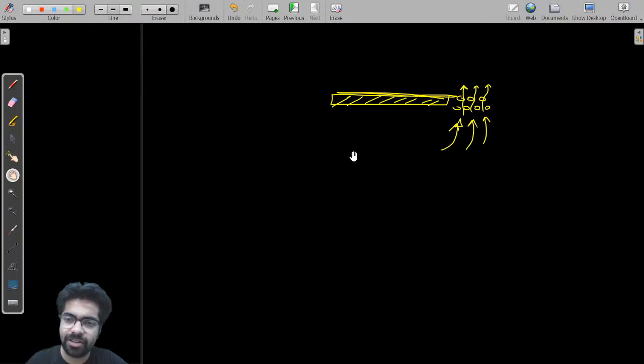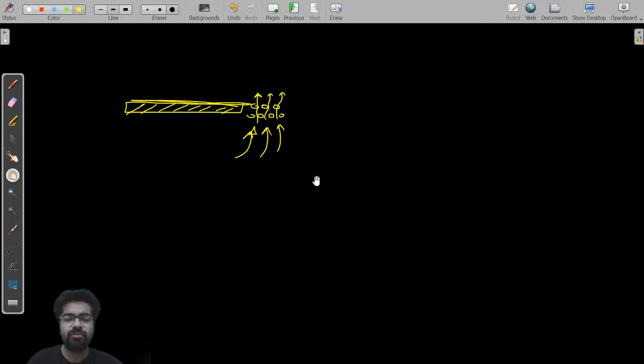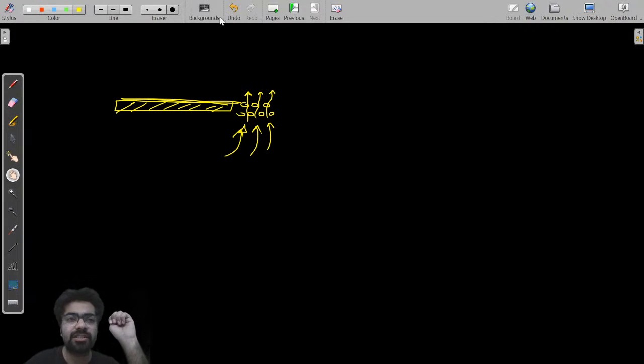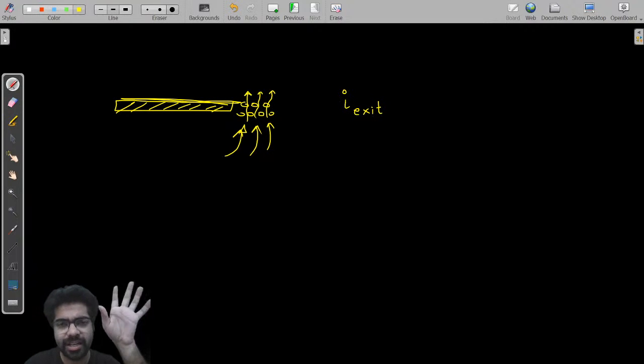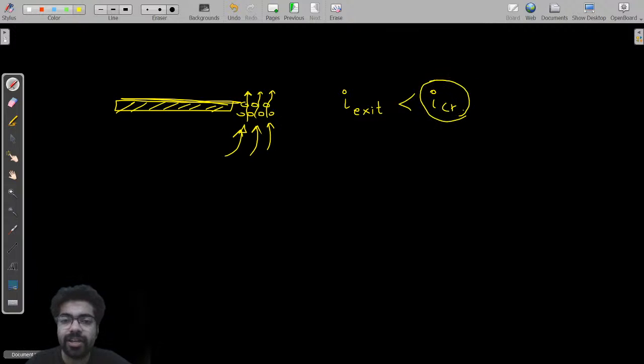Okay, dear sir, I have understood this. Now listen very carefully. You should appreciate these three facts. If this exit gradient, or simply hydraulic gradient, is less than the critical value, then there is no problem. We are safe, and no undermining will take place.